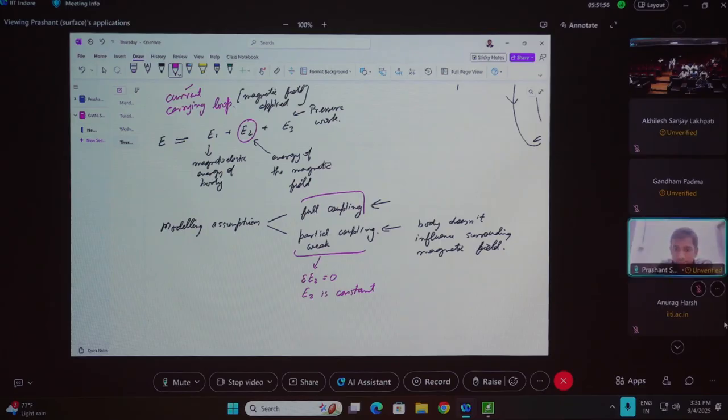In the case of magnetic field, that's the main difference. You basically calculate what the magnetic field is, then the solution procedure is pretty much the same. You apply the same shooting method using ODE, and then you can look for different types of instabilities. You can look for wrinkling instability, limit point instability, and so on.